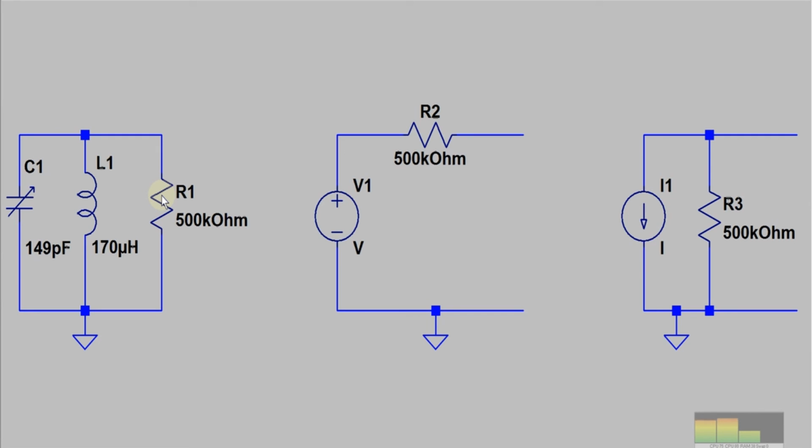We know that a tank circuit with a receiver coil for electromagnetic radiation has also an output voltage, and so we can look at the lossy resonant tank circuit as a voltage source with an internal impedance of exactly this parallel resistance.